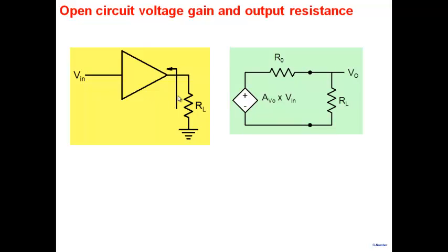Whatever resistance is, whatever current source is, whatever it has inside it, I can always write a Thevenin's equivalent of it. So when I look at an amplifier from the output, I can describe it by these two. You can see here, this is like a Thevenin's voltage, and this is like a Thevenin's resistance here. Okay, so when, in the context of amplifiers, when I look at it from the output port, I describe it by a resistance, Thevenin's resistance, if you would like. We call it a output resistance R0.